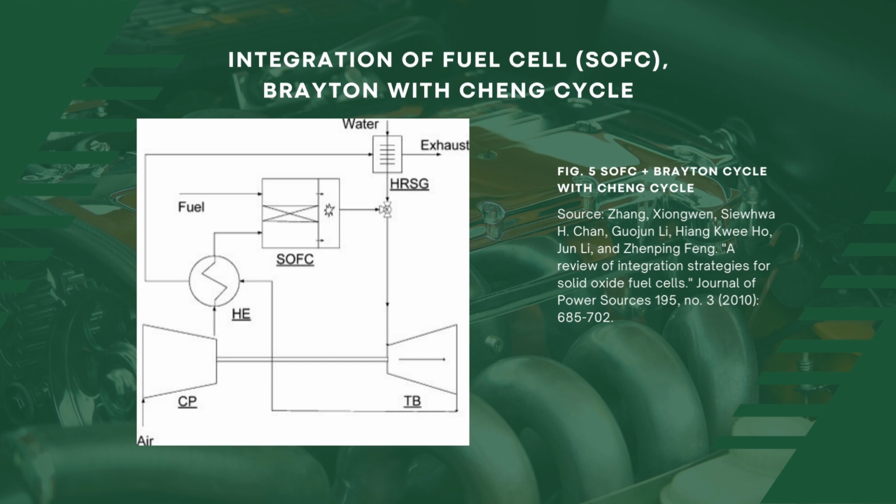The heat recovery steam generator is added for producing steam, which is injected into the gases before the turbine. The exhaust heat is utilized in the HRSG, thus increasing the system efficiency. Here I am talking about system energy efficiency. Because the turbine is a mass flow device, combining the steam with high temperature gases increases the total electrical power produced. Part of the steam produced in the HRSG can also be used as a steam load.